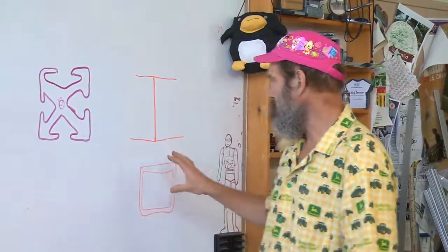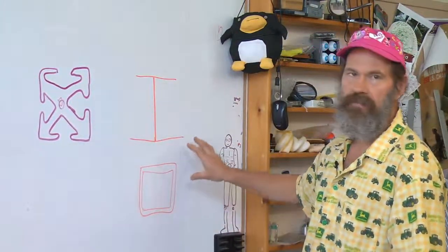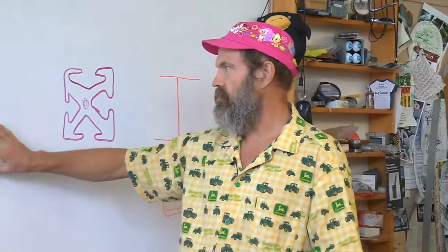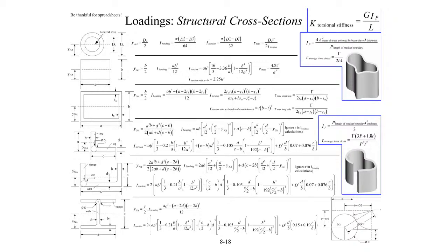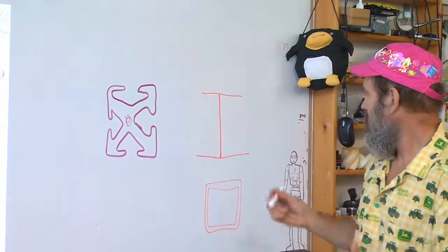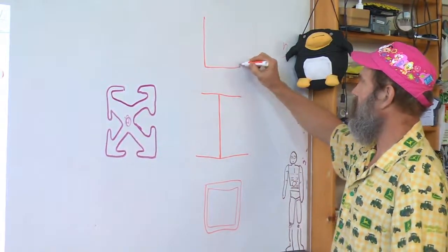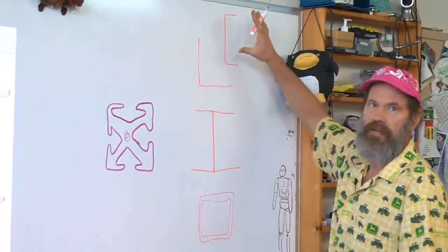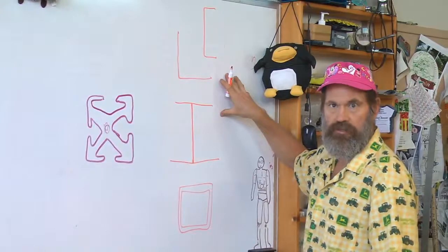Now, the torsional stiffness of these open sections can be very easily determined, even some more complex ones, by these simple formulas, or the more complex exact forms for some common shapes are given. But any of these open sections, while they're very useful in bending, remember they're basically useless in torsion.